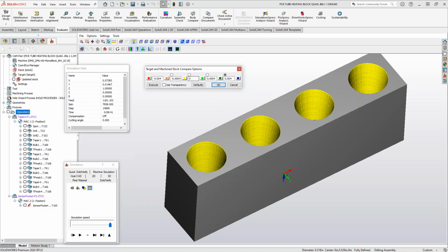But that's a really good point. I never thought of that, because again, these are facets, triangles, elements, whatever we want to call them, in the background that build this thing, and they look at, in terms of surfaces, the vector of that surface, kind of like we talked about every time we do HSS, that surface normal, that surface vector. And if you set this to 0, there's no direction. It's either a negative or a positive. It can't be neutral. So that's a good idea there with the 0.